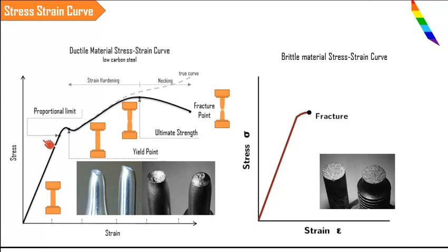So the rate of change of stress and rate of change of strain will be the same. So a straight line behavior is going to be obtained up to the proportionality limit. And when we move further forward, we have another point which is going to come over here, very close to this proportionality limit, somewhere here.